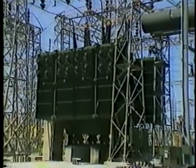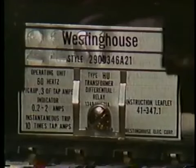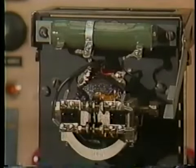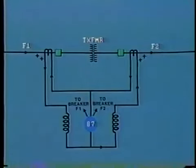Where differential relays are used to protect large power transformers, it is usual to fit yet another restraint unit into the scheme. And this is harmonic restraint. This unit acts to prevent inadvertent tripping of the differential relay due to transformer inrush current. What do we mean by this?